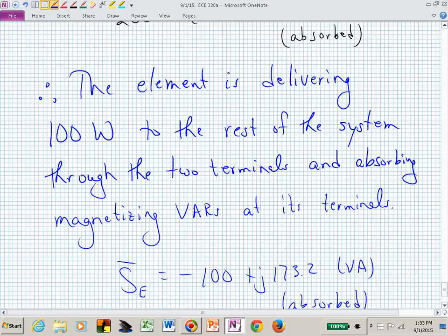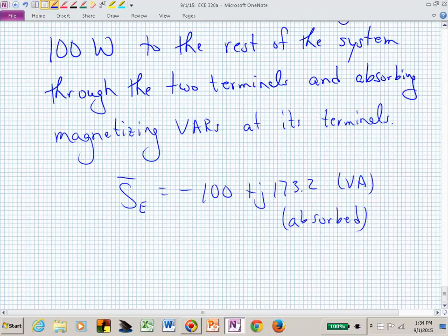So now you could say it's, I don't know, negative magnet. It's now basically you're storing energy. I like to just say you're storing energy in the magnetic field, or you're storing energy in the electric field when it's capacitive. But a lot of times you'll see with many industrial facilities, they are mostly inductive, and so that's why this magnetizing VARs is maybe more common.